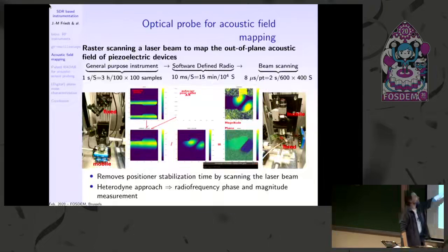If you take your basic experiment, you're going to see what it looked like initially. You had this positioner. What I call the positioner is this little sliding stage, one in X, one in Y, and you want to position the sample with sub-micrometer accuracy. So it actually takes a bit of time for the servo to settle. Actually, what you realize is it takes about 10 milliseconds for the servo to settle.